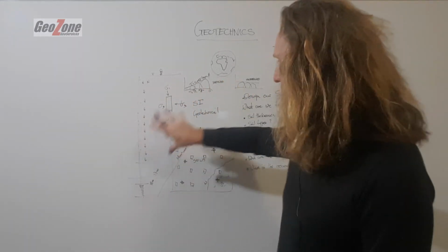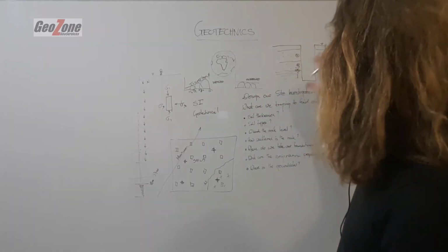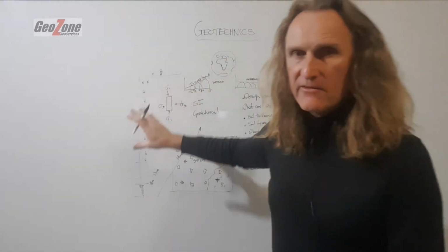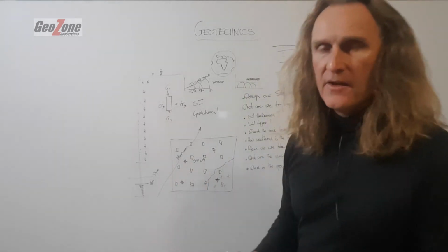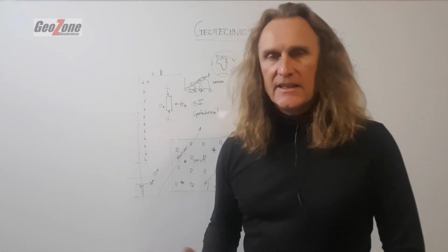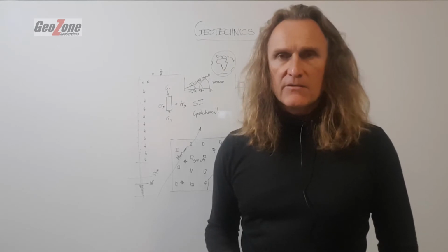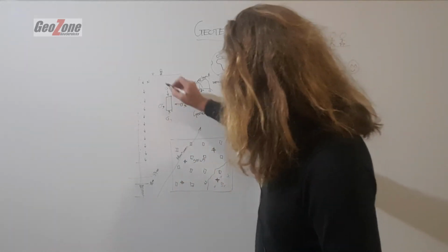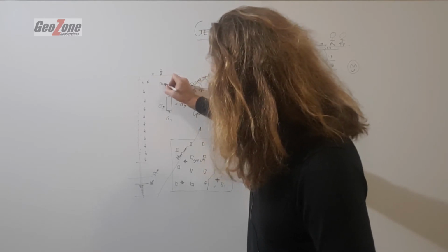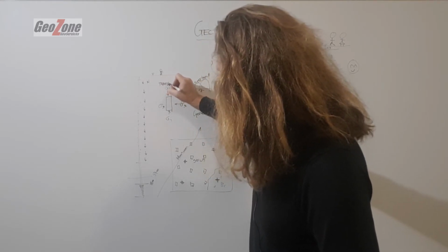So we understand what's going on, we take our samples, we test them, and for slope stability we can use c and phi, which I spoke about earlier. We use c and phi in our analysis of the stability of the slope. So that's a triaxial test. Okay, let's just write it here. We're getting a lot of information coming at you. Triaxial test.